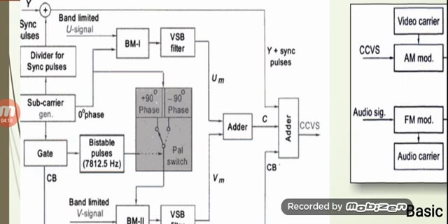What does this mean? Whatever the horizontal synchronization frequency that we use here is 15625, where each line will be getting scanned by a frequency of 15625. Then if we use the frequency exactly half of that, then instead of taking every line, every alternate line will be selected.